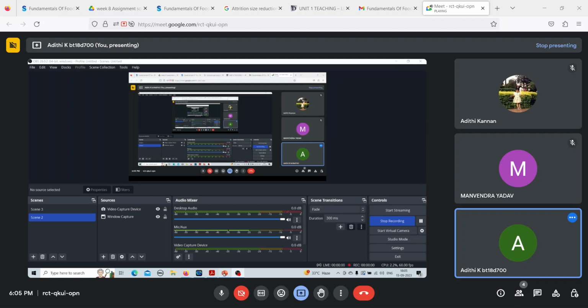So you can call it Kb here. This entire constant is known as Bond's energy constant, which is given as 3.02 in the question. The mass flow rate of the wheat grits is given as 100 kg per hour. The xf, which is the particle diameter of the feed, is given as 3 millimeter. We are reducing it to 0.1 millimeter. So this is just basic substitution here.